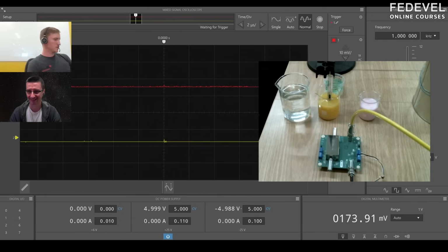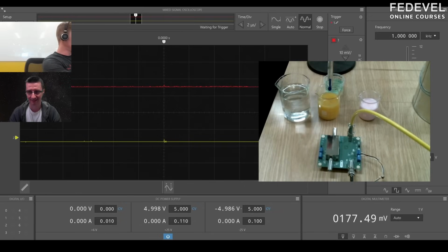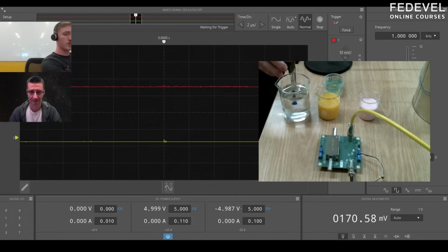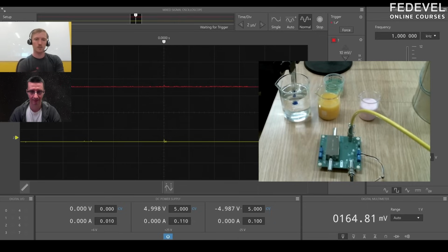Good. So now we can go ahead and move on, and I'll just rinse it off in this deionized water here. One thing to note is this is deionized water, so it should have a pH of 7, just about neutral, but we're still reading as if it's an acid, and that's because this water is deionized. So this probe actually measures the ionization activity, and there's very little ionization activity in here, so that can give you a false reading.